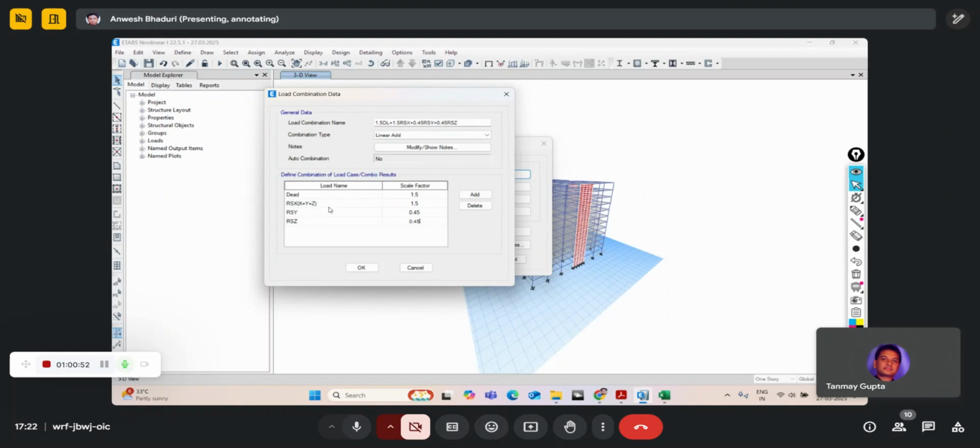And then the software will identify it as a load case and make all the possible combinations. But in general, say I'm making 50 load combinations. I'll tell you one way how it can be done. There's an interactive database editor available in ETABS, which makes use of Excel, and you can automate this also if you feel like.